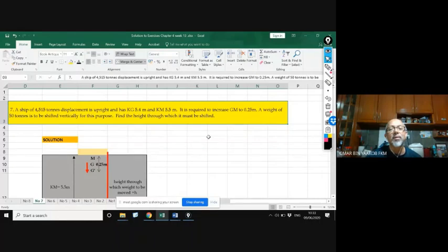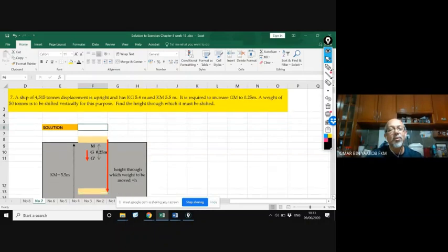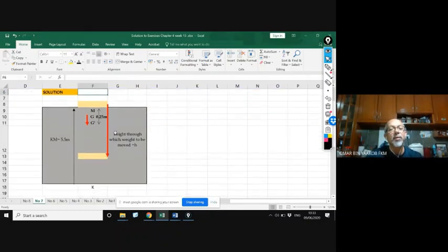So moving weight. Naturally you need to think, which way should it move? Say there's a weight anywhere, whether it needs to go up or down. When you want to increase GM, you have to reduce KG. If you want to reduce KG, you need to move the weight down so that G can move to G dash, which is lower. So that's basically the solution here.